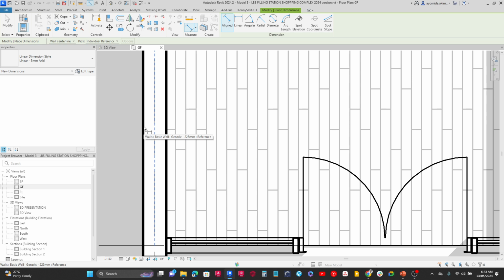So this is quite a tricky tip in Revit. If you are not getting the right reference once you've moved your cursor to the particular element you want to measure, all you need to do is press the Tab key, and now it will move to a different reference. Right now it is set to the edge of the wall. If I click there, I can move my cursor to the other edge, and if it is not selecting that reference, I just press the Tab key again until it moves to the reference I want.